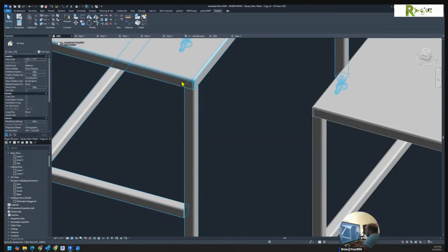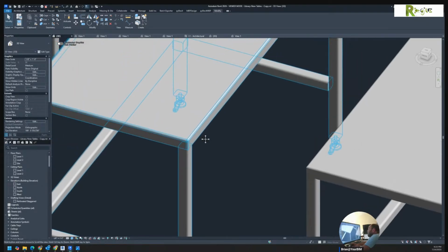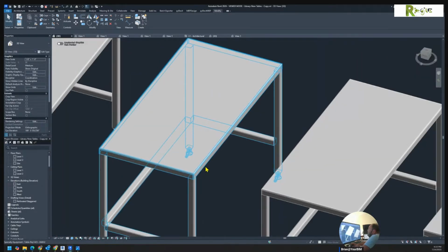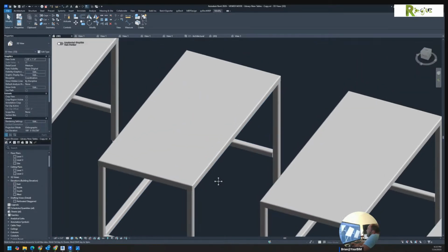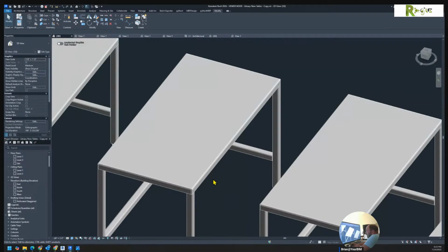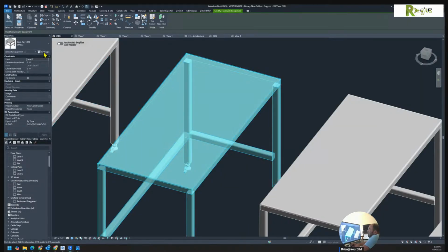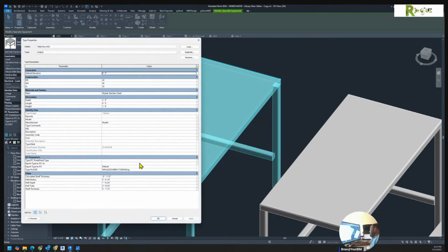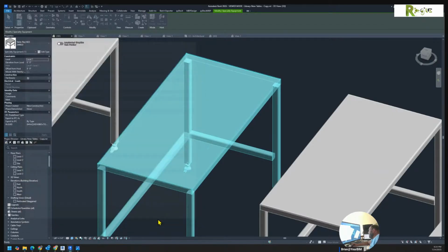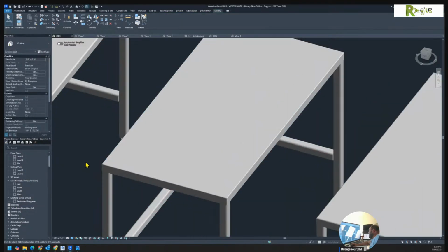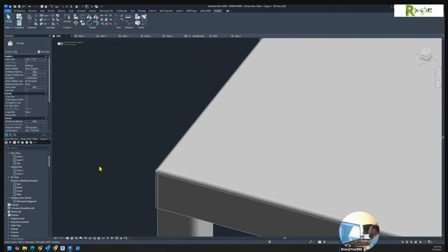That's the benefit of the method of putting these fillets on, which seems a little bit awkward. Typically I would not fillet anything smaller than a 1/4 inch. But believe it or not, we'll test this. This is the first time I've ever tested this. I bet I can take that fillet radius down to an 1/8 inch. I wouldn't recommend it, but you would find that it would still keep those two lines.